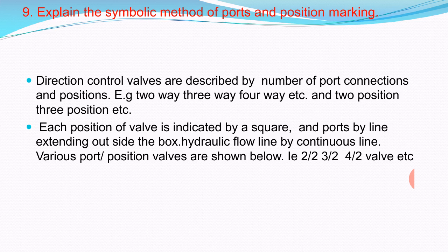Now question number 9, explain the symbolic method of ports and positions. Different direction control valves are used in a hydraulic system. Direction control valves are described by number of port connections and positions. Example: 2-way, 3-way, 4-way, etc. and 2 position, 3 position, etc.